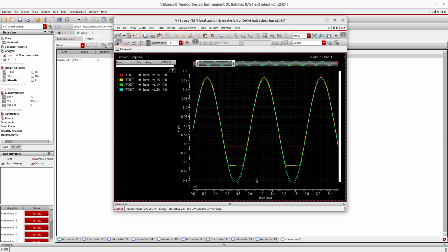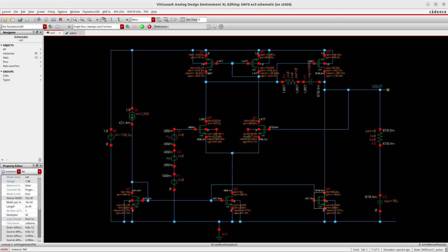Okay, so, important again, to summarize this part: the dimensioning of the output stage is extremely important. Both the voltage swing and the current that is fed to the load need to be dimensioned correctly. I mean, there is the load and there is also the feedback. In this case, there is no feedback because the output is directly connected to the negative input, it is a buffer. But if there is feedback, we will also have to dimension for the feedback. An important detail is that it is not only the resistances that have to be considered. We need to consider also capacitors.